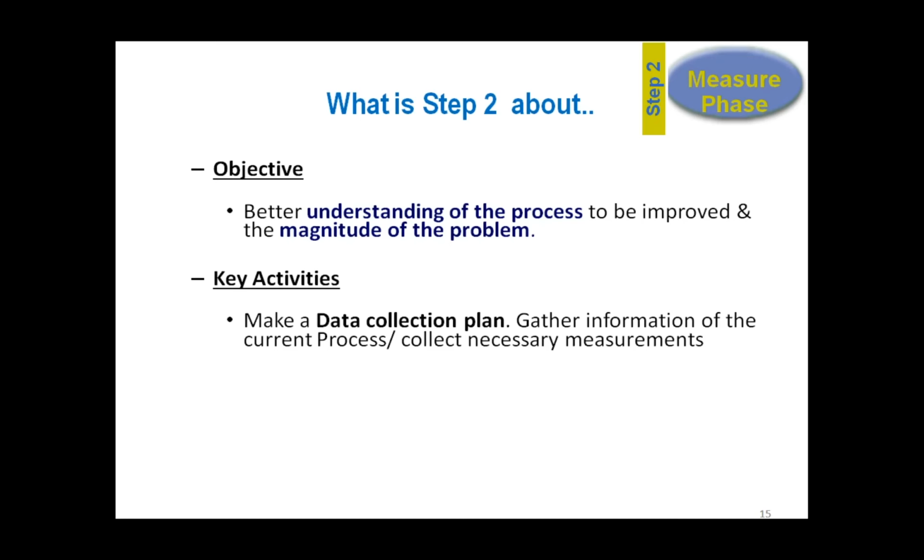So, for example, if it is for the defects that we are talking about in the assembly area, probably we need to know, for the particular part, who is the supplier, what shift the product is getting made, who are the operators who have worked on that shift or on that particular part, at what time was that part made, what was the specification of the raw material that was used. So these are the various kind of aspects that we might need in the analysis phase later on, and that's where we need to make sure we capture all this data right here.